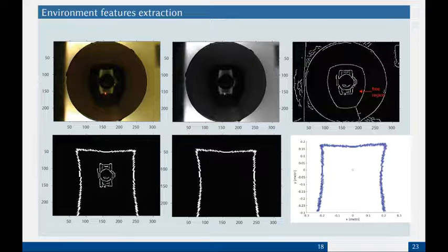Using the geometrical model of the omnidirectional system and an interpolation algorithm, it is possible to undistort the original image. Although the body of the camera is still visible, knowing its pixel coordinates, it can be easily removed from the scene. Finally, each extracted landmark is mapped into the world frame. Then a geometrical parametrization of all landmarks is computed.